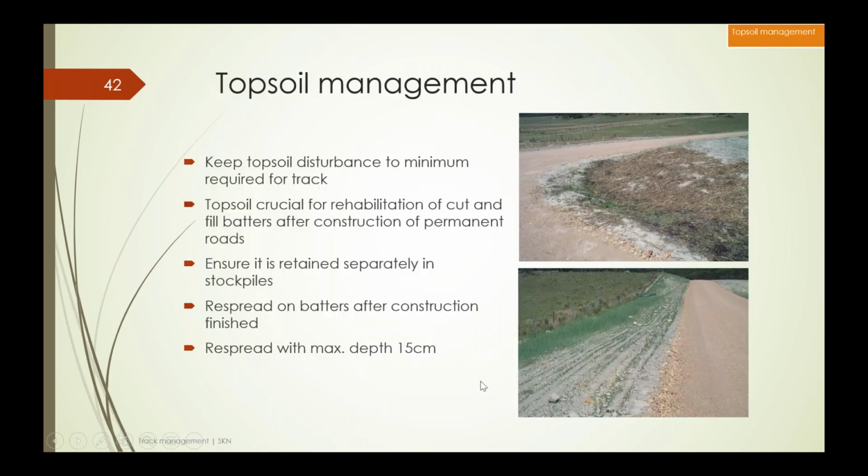When you're building a road, you'll be scraping off topsoil, and it's a pity just to see that topsoil wasted in a windrow or a pile or in a batter. So give some thought to managing the topsoil so that you can reuse it to help maintain the stability of the batters.